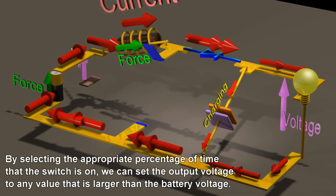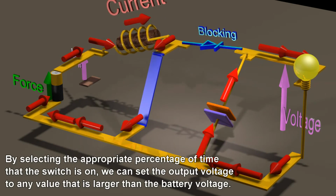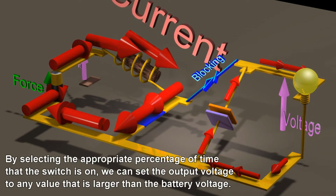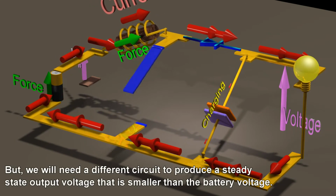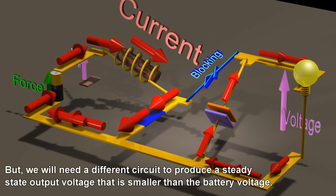By selecting the appropriate percentage of time that the switch is on, we can set the output voltage to any value that is larger than the battery voltage. But we will need a different circuit to produce a steady-state output voltage that is smaller than the battery voltage.